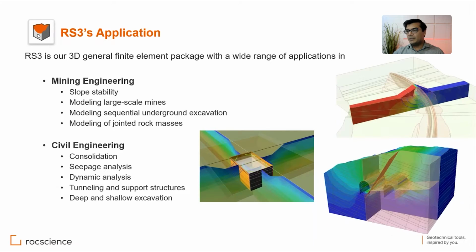And for civil application, you can do consolidation, seepage analysis, dynamic analysis. With the tunnel designer tool that we offer in the program, you can define sequential excavation for tunnels, define different support elements such as liners, bolts, beams, and piles, and you can do deep and shallow excavation.